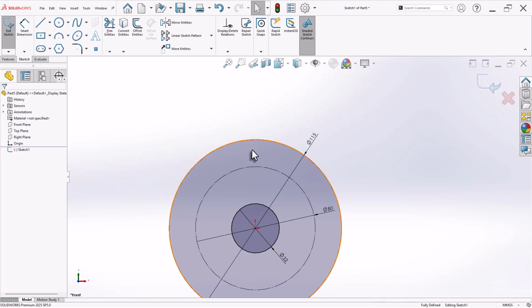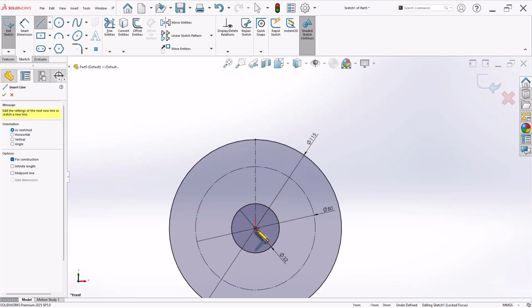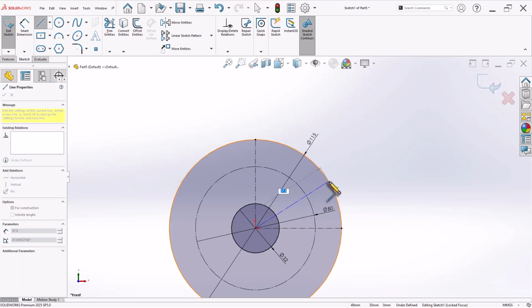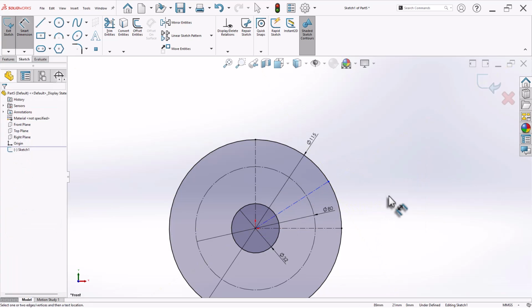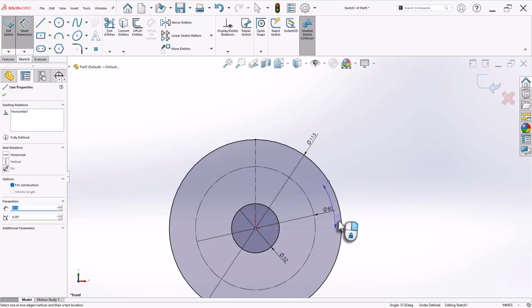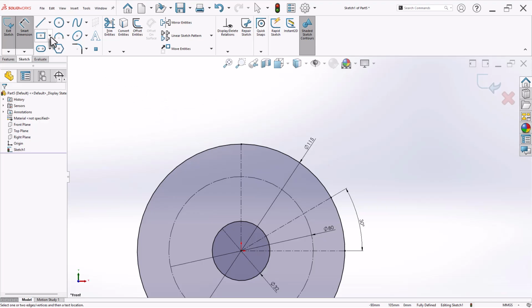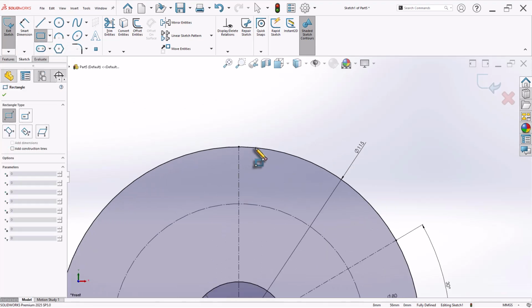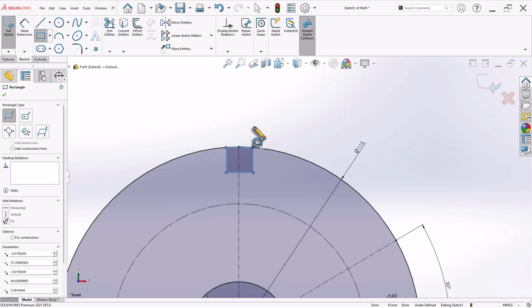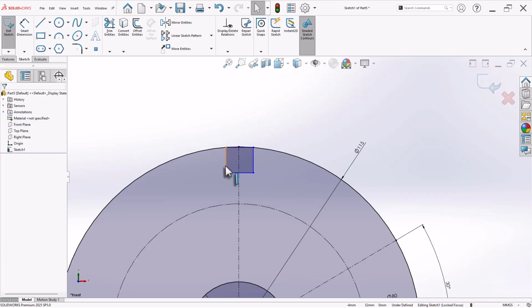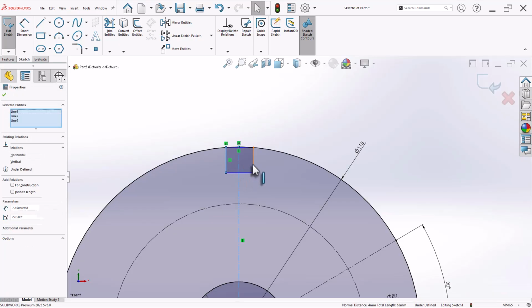Here we can either create a cut over here and place the circle and create the circular pattern of those things. So let's try in that way. Second center line and third reference line, which is exactly at 30 degree. So let's first place the corner. So let's make these two vertical lines symmetric.